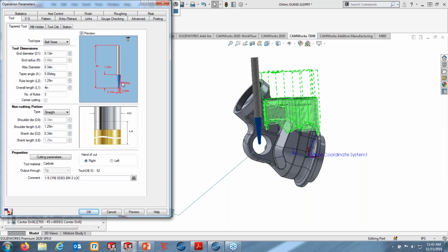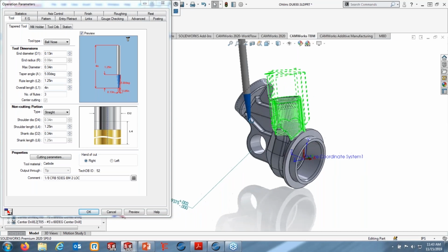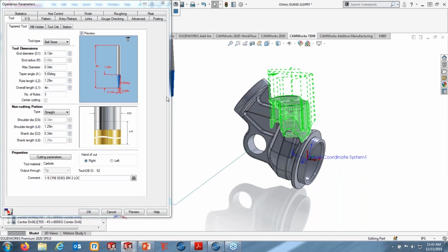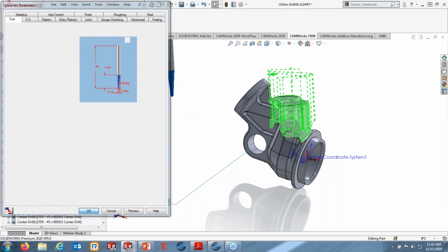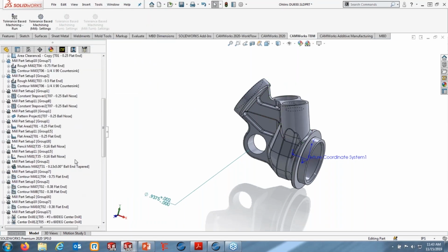If you're talking about true barrel cutters, where you've got an actual thing that looks like a beer barrel or a keg at the bottom with a big radius to run down a wall, sure, that's a barrel cutter, but a conical barrel cutter is not. It's just a tapered ball end mill. So just be aware of that. Essentially, we support tapered ball end mills. If your software doesn't, then you've got to question how good of a 5-axis tool it really is. In here, we can support and program through those. But that kept coming up in questions quite frequently during demonstrations, so I figured I'd touch on that whilst everyone's on the phone here.